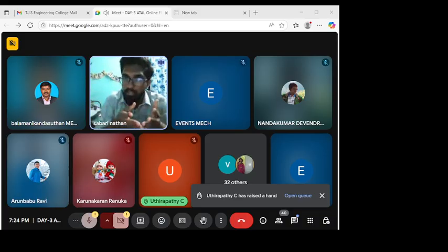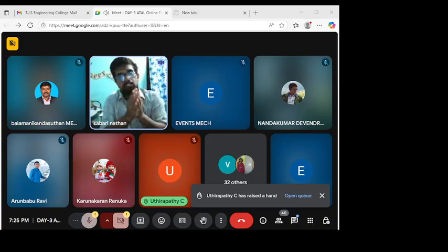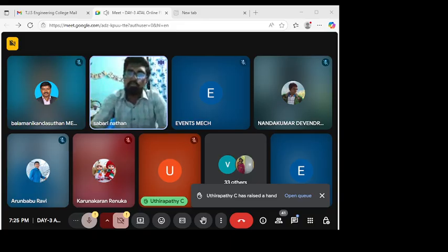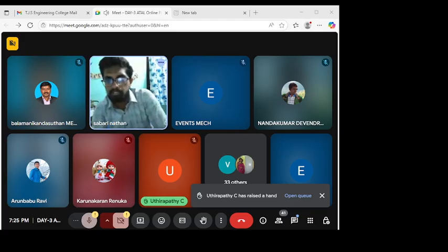If you are going for bioprinting now, the nozzle should be selected based upon your requirement only. Based upon the selection of your nozzle size, your print resolution should be decided. Apart from that, after printing, you can use secondary processes like sanding and chemical vapor smoothing steps to improve the print resolution. So these are some other things.